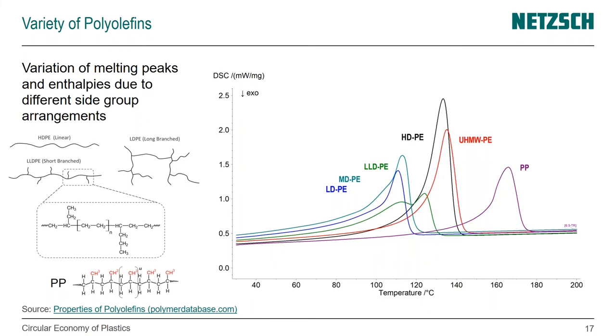Okay, and someone said they missed the first part, and I actually didn't explain how we prepared the mixed plastic samples for the LDPE PP study that I showed. Mostly, we literally just chopped pellets into smaller pieces, really small pieces, and put the different pieces in the pan. For the HDPE PP study, where you also saw as an outlook a good agreement, here we wanted to really blend the material, and we performed blends on a twin screw extruder, and we worked with a company to obtain those.